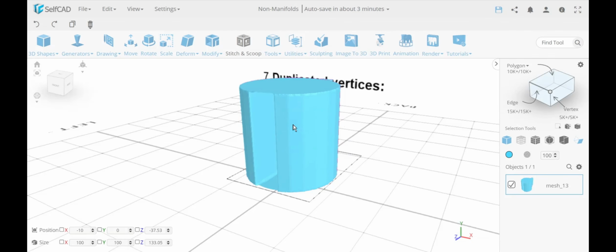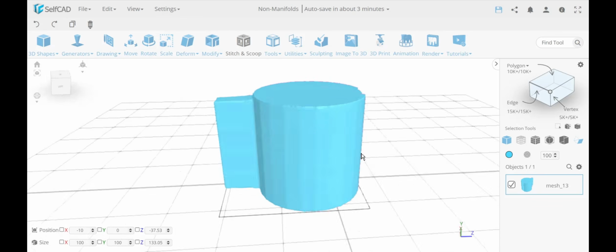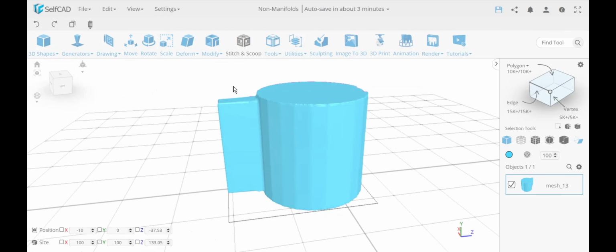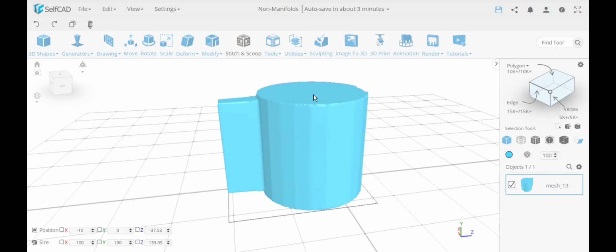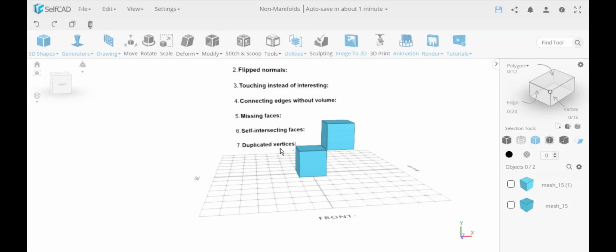And again, as I said before, it's worth watching the other video, the link in the description, where in some cases Magic Fix is really helpful. But for these cases, it's much easier to solve it yourself. If flip normal does not flip it, if you see they're simply pushed in, like flipped inside self-intersection, where one thing pushes out from the other side, you simply push them back in, and that should solve it.